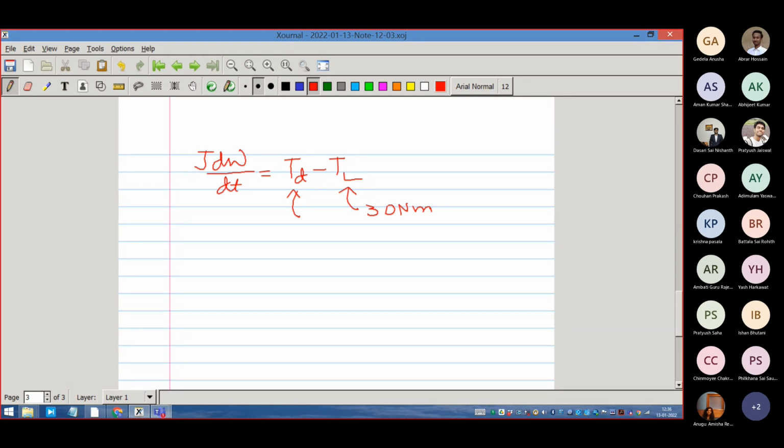So what is the consequence of that? Then J d omega dt is positive. So therefore, what is happening? The rotor speed, this omega is rotor, will be increasing. And what is the implication of rotor speed increasing? Implication of rotor speed increasing is slip decreasing. So you see that it is going in the correct direction. That's why we have chosen this slope to operate on.